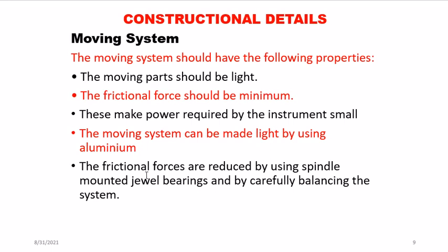And the frictional forces that we said should be minimum, it is possible for us to reduce them by using what we call spindle mounted jewel bearings. The bearings that are responsible for the smooth movement, we can use this type, spindle mounted. And it is also very possible to reduce our friction by carefully balancing the system to make sure that everything is in the right position.